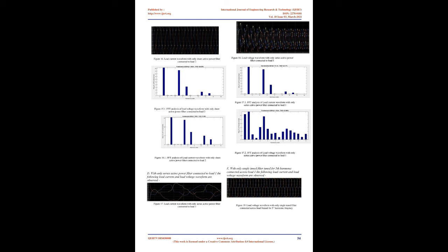Vd and Vq voltage outputs of the current controller are converted to 3 modulating signals Uabc_ref used by the PWM generator. The control system uses a sample time of 100 microseconds for voltage and current controllers as well as for the phase locked loop, PLL, synchronization unit. Pulse generators of boost and voltage source converters, VSC, use a fast sample time of 1 microsecond in order to get an appropriate resolution of PWM waveforms. 6. 10 kVAR capacitor bank filtering harmonics produced by VSC.